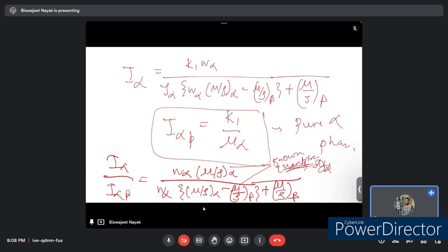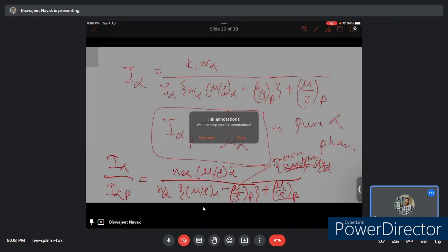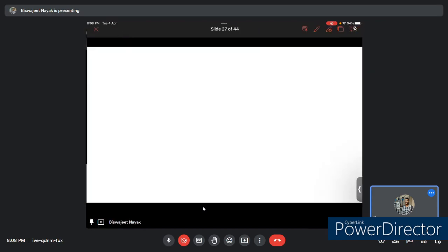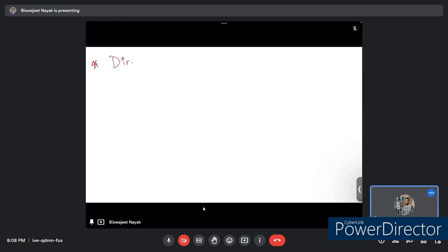For the direct comparison method, this method doesn't require a sample of pure phase because the required reference line comes from another phase in the mixture. So it is of great interest because it can be applied to polycrystalline aggregates too.